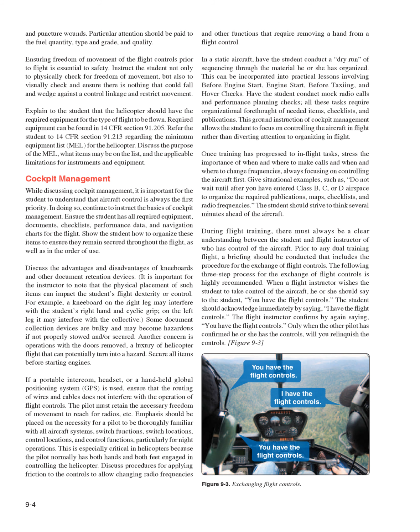It is important for the instructor to note that the physical placement of such items can impact the student's flight dexterity or control. For example, a kneeboard on the right leg may interfere with the student's right hand and cyclic grip, on the left leg it may interfere with the collective. Some document collection devices are bulky and may become hazardous if not properly stowed and/or secured. Another concern is operations with the doors removed, a luxury of helicopter flight that can potentially turn into a hazard. Secure all items before starting engines.